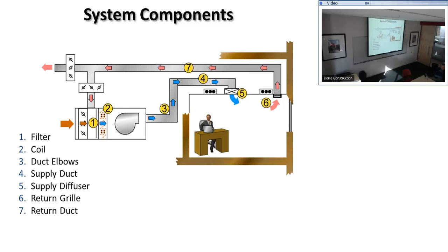What we see is an opportunity for the job to save cost. Fundamentally, the decision of your cable is just a cost thing. Otherwise, I have two parallel systems here I'm paying for, where my return could just drop in. Even this space here, you want to have supply, and wherever you're going to drop through the roof, you just have a return right there. Even if there's a ceiling there, if it was a plenum, I would keep the return there. Otherwise, I have to put all this duct in every one of these offices. So it is a parallel duct system.